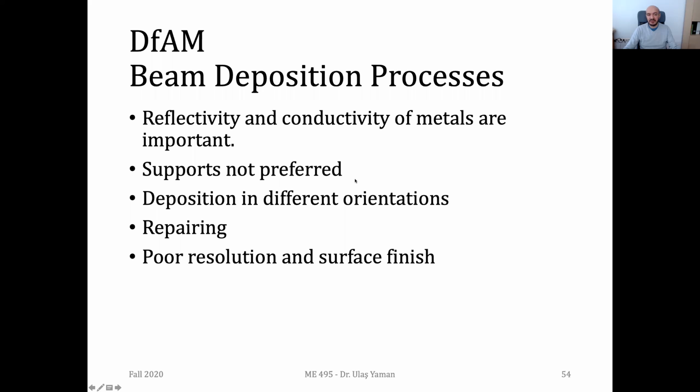In some cases, it may be necessary, but it's not preferred. Instead, what they do, they have multi-axis systems. Since they are jetting the powders at very high speeds, they can also do deposition at various angles. This is somewhat similar to multi-axis fused deposition modeling. And we talked about it many times that these processes are highly useful for repairing purposes.